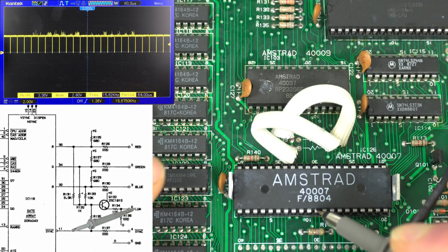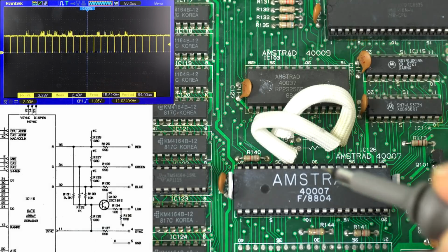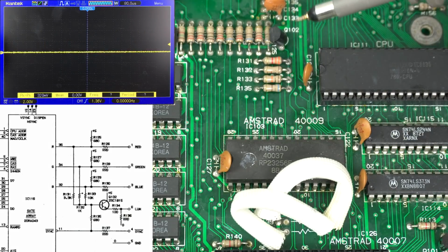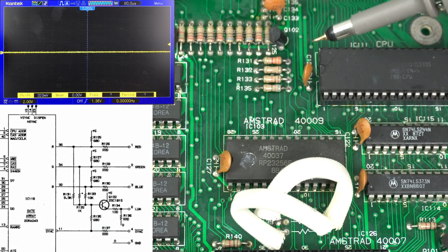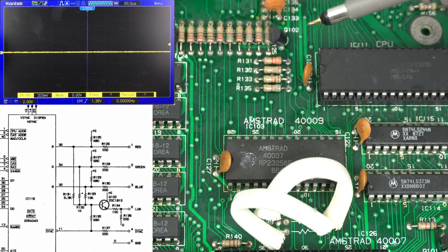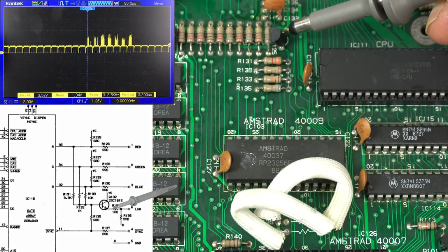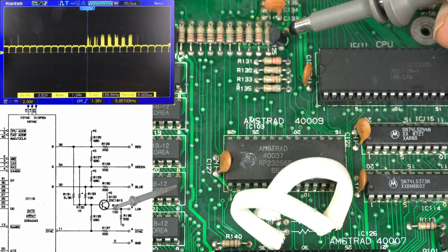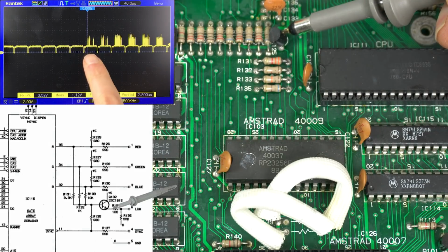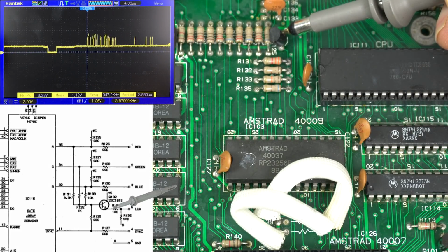So I wonder if that was related to that particular RAM IC. Huh. Okay, but we'll go back to that in a second. Now that we know what those things are like, the luminance signal is supposed to be all three of them put together. And I believe the output is this part of the transistor. And yeah, actually that's exactly right. That's probably blue combined with RGB in those places and the sync signal. So yeah, that's exactly right.